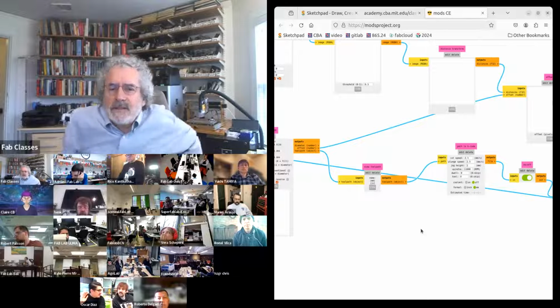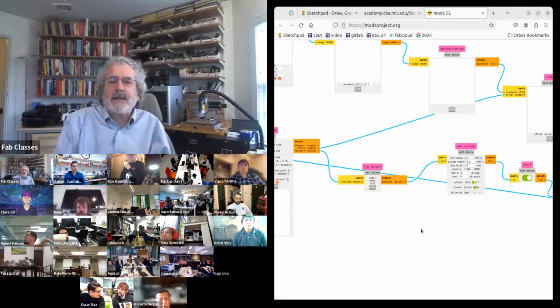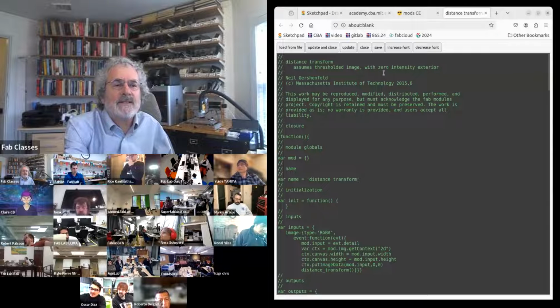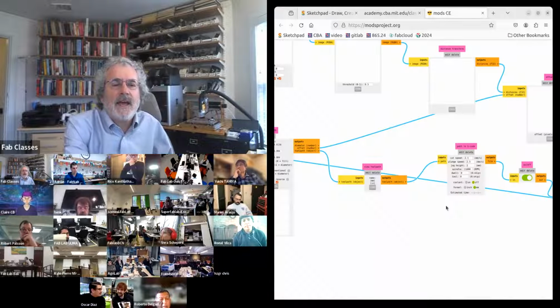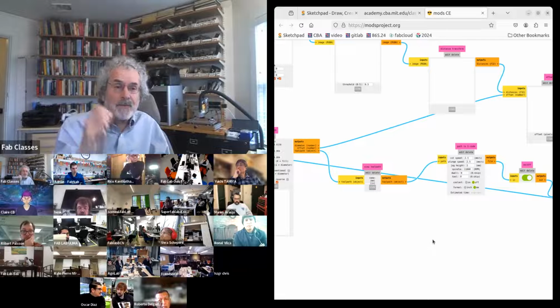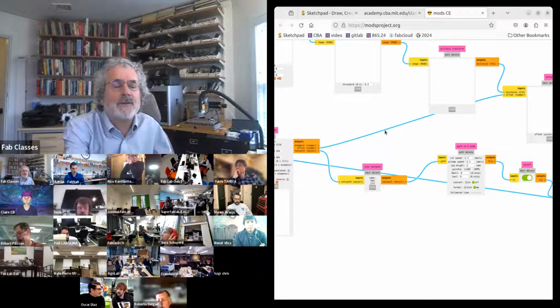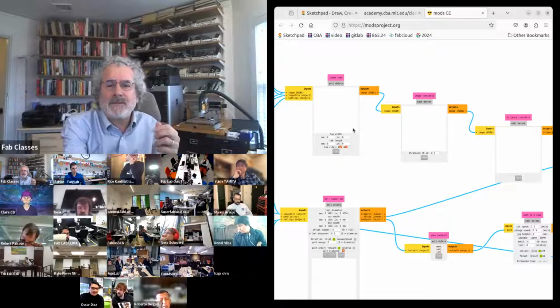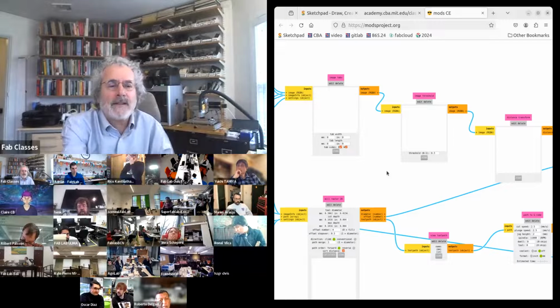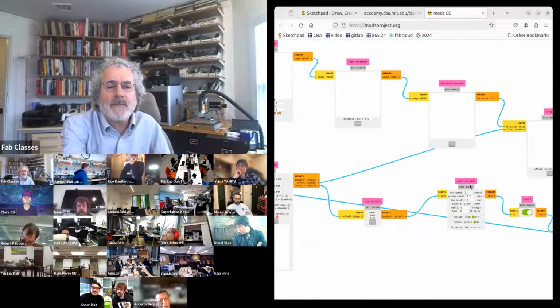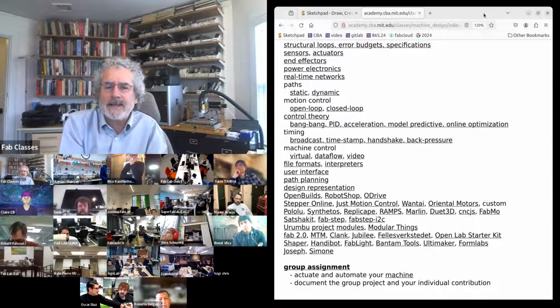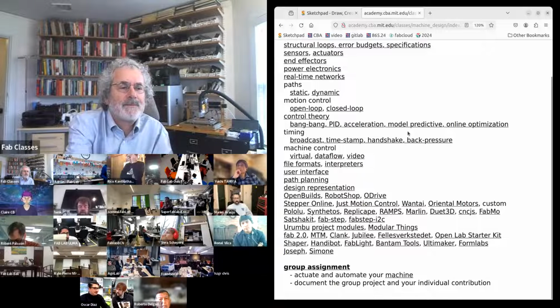And so one of the reasons I wrote mods, really the reason I wrote mods, is you can open up each of these and see what's going on inside of them to see the algorithms. And if you need to change the workflow, you can add or remove modules. Like I needed to put in tabs, so I didn't vacuum up parts, so I added this module. And if you want all of this, but you want a different format, you could change this module. And so that lets you see what's going on under the hood in the path planning and lets you interact with it.